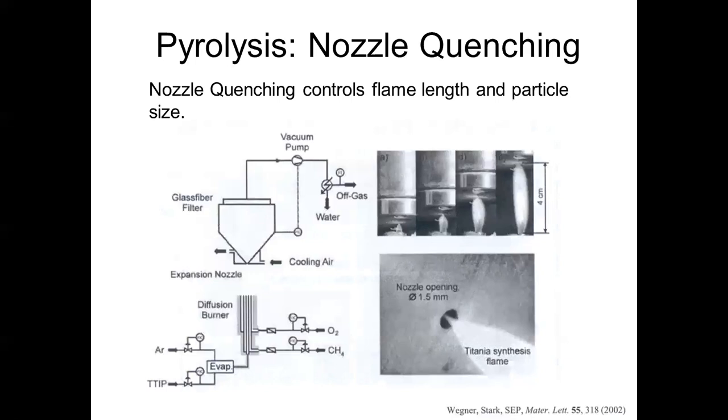So to control the paint, or the titanium dioxide powder, the quality of those nanoparticles is going to be extrapolated to the quality of the paint. This is what we're going to do. And interestingly, that's going to control things like the UV properties of the paint, or UV absorbing, so that the paint doesn't fatigue over time.